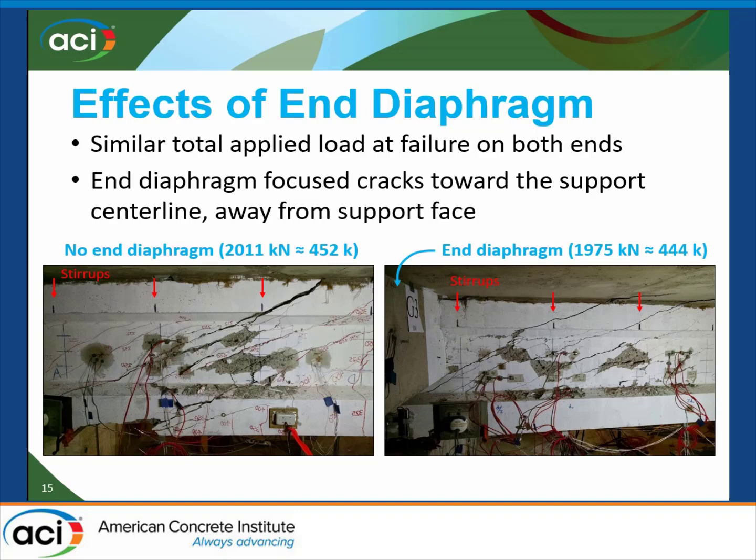What was interesting that I didn't mention is we did some other tests on similar beams that went down to like an 8-inch spacing or something much more normal for the end of a girder. And when that tight of a stirrup spacing was available, the first web shear crack that appears, if we unload the structure, kind of disappears. So it may not be visible if you have an overload. But with this really wide spacing, we had a unique chance to see, hey, if we crack the girder and take the load off, can we still see it? In which case, yes, without more stirrups.